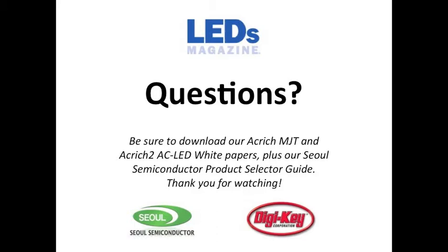Electrolytic capacitors can go dry, and their typical life is going to be around 10 to 15,000 hours. So what we've come up with is an IC that will drive our multi-junction technology LEDs in a system that does not require your typical electrolytic capacitor or your typical conventional driver. So it saves a lot of space, it reduces the thermals of the overall system, and its life is around 87,000 hours. So that's kind of what we're doing with our IC specifically.